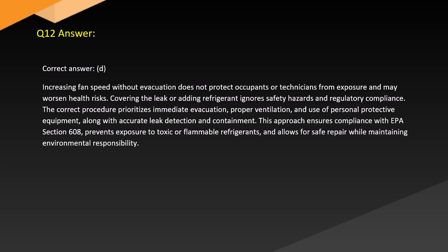Answer. Correct answer. D. Increasing fan speed without evacuation does not protect occupants or technicians from exposure and may worsen health risks. Covering the leak or adding refrigerant ignores safety hazards and regulatory compliance. The correct procedure prioritizes immediate evacuation, proper ventilation, and use of personal protective equipment, along with accurate leak detection and containment. This approach ensures compliance with EPA 608, prevents exposure to toxic or flammable refrigerants, and allows for safe repair while maintaining environmental responsibility.